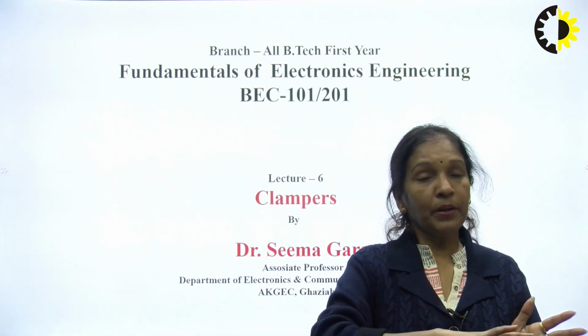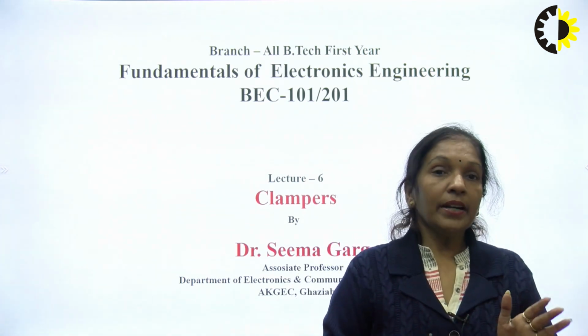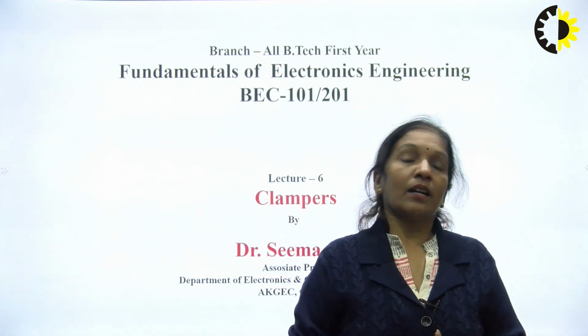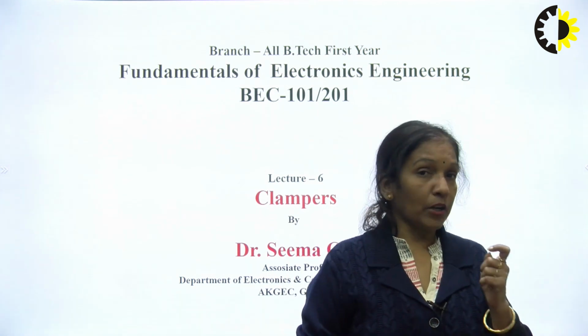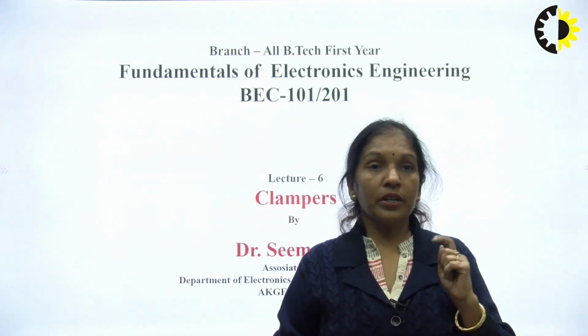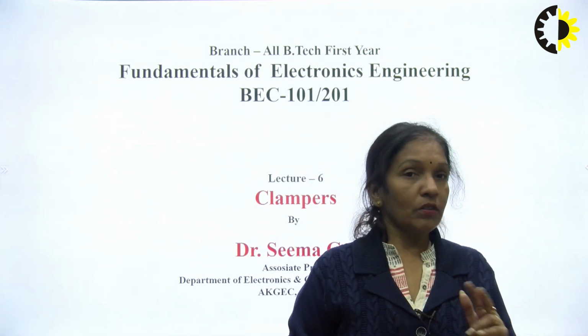It will never be fully charged, and that is the reason we wait until our diode comes into forward bias and our capacitor gets fully charged, so that we can start the analysis. So that is a very important point: wait until the diode is forward biased for the first time.